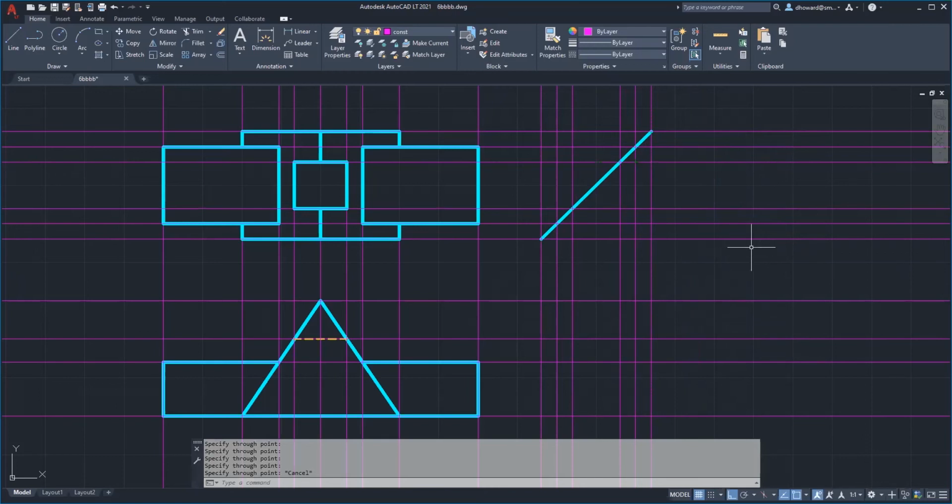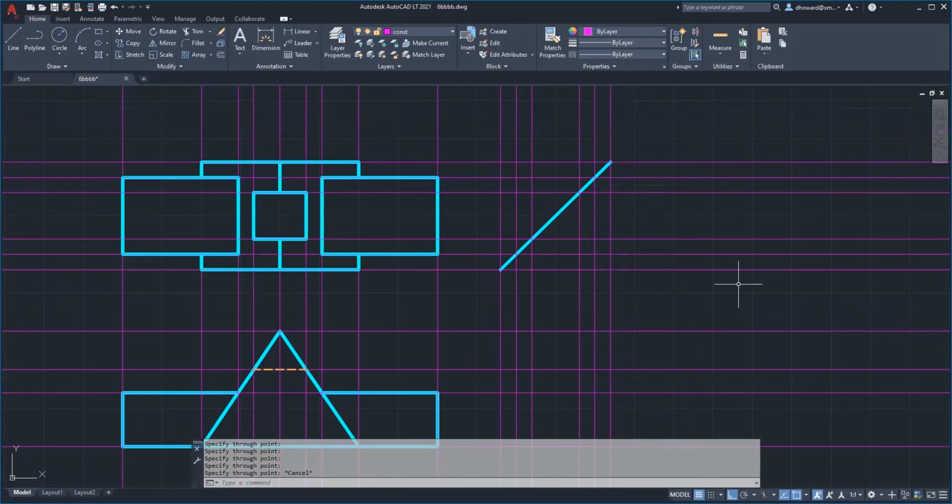I'm going to point out another fun thing you can do to reduce confusion, and that is to trim these construction lines to the transfer line. The regular trim is just TR enter, which is what I just did. But if you look down here, there are some options. And if you choose cutting edges by simply typing T, you can see it has a capital T down there.